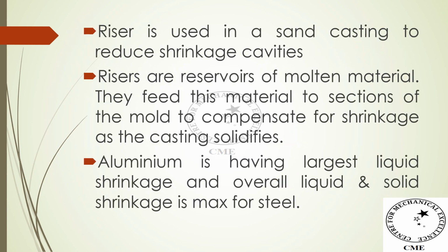Riser is used in sand casting to reduce shrinkage cavities. Risers are reservoirs of molten metal. They feed this material to the section of the mold to compensate for the shrinkage as the casting solidifies.